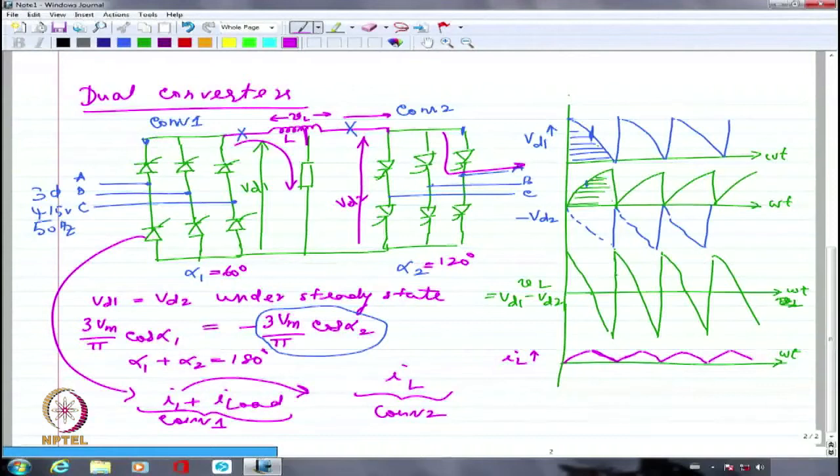And currently I am drawing a lot of power from the AC side towards the load. So the load is eating away everything, whatever it is doing. It is doing some work. So what is actually going as the circulating current is the small portion of the power, or you can say reactive power in this case probably, which is flowing back to the AC mains, nothing else. So this is clearly working as a rectifier and this is clearly working as an inverter, a line commutated inverter.